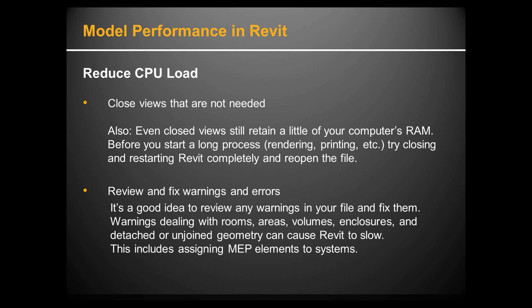So yeah, close views that are not needed. There's some tools you can do with that, and some other related items, some best practices. Also, reducing the CPU load, fix warnings and errors, and I'm more familiar with the MEP side, but also if you have rooms, if the rooms are overlapping, wall cleanup, walls and roofs, I don't know what kind of errors you run into, rooms that are not an enclosed space. Let me go and open my file.